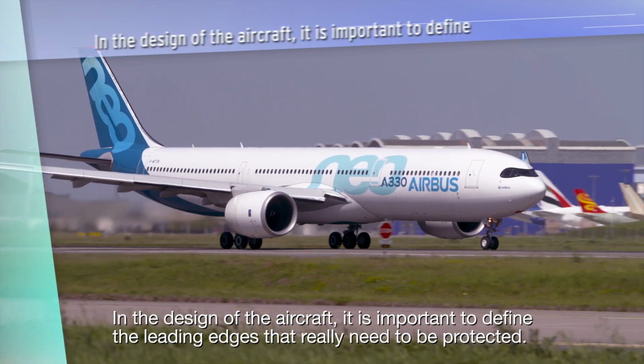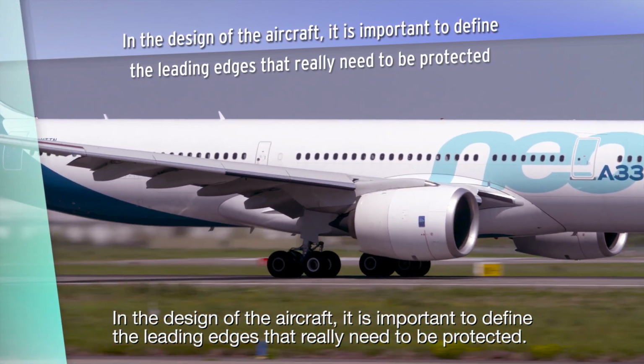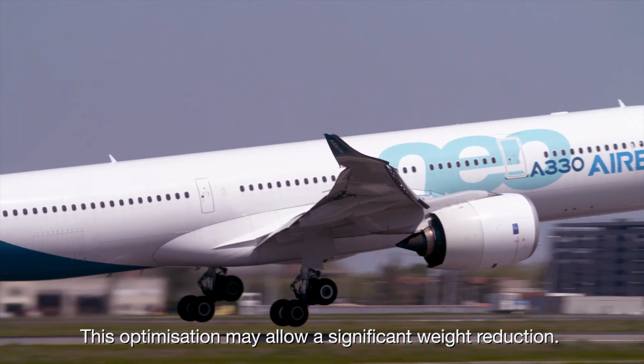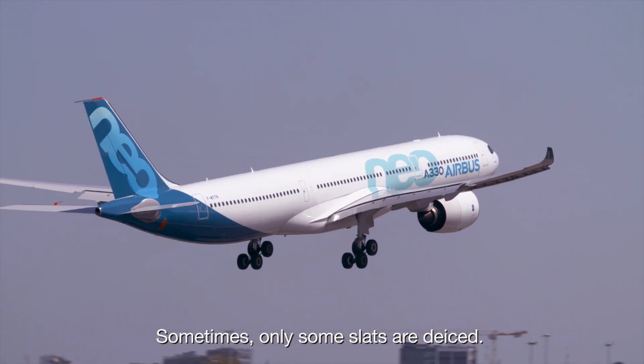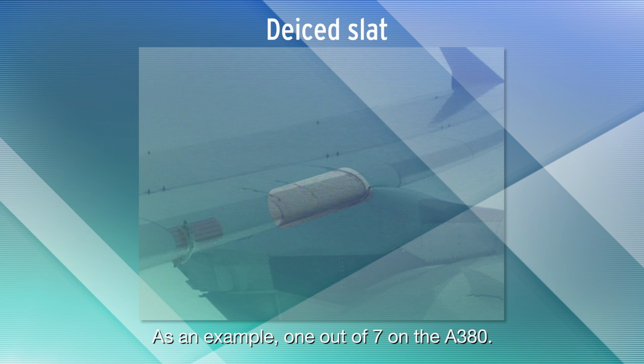In the design of the aircraft, it is important to define the leading edges that really need to be protected. This optimization may allow a significant weight reduction. Sometimes only some slats are de-iced. As an example, 1 out of 7 on the A380.